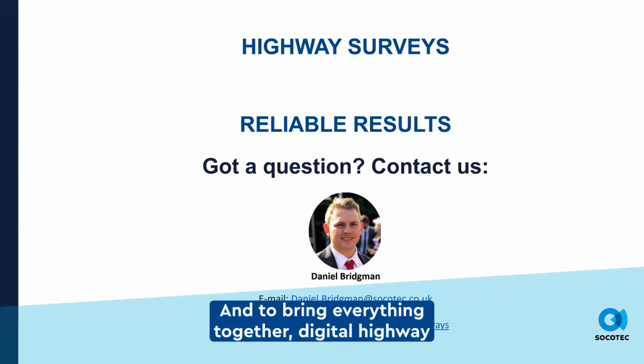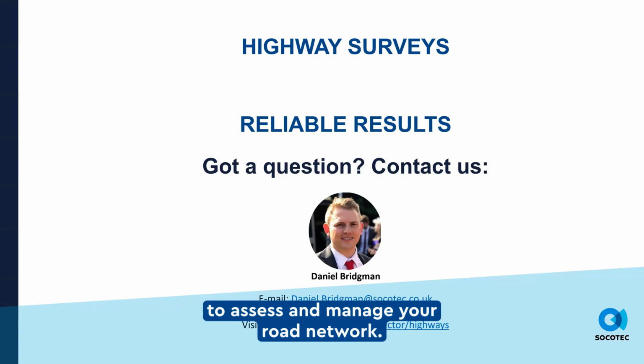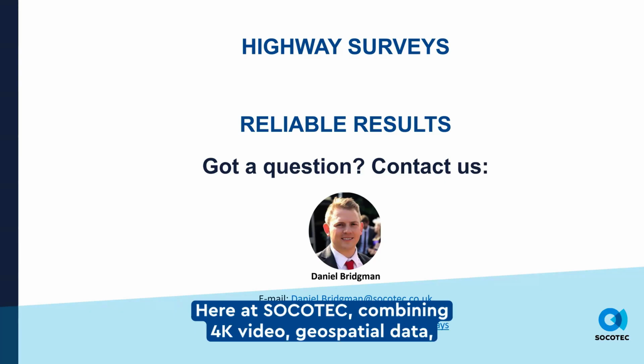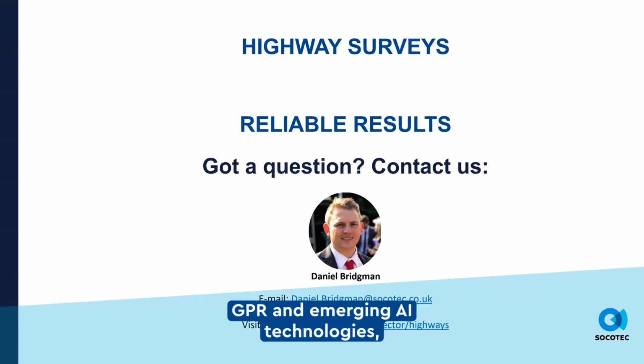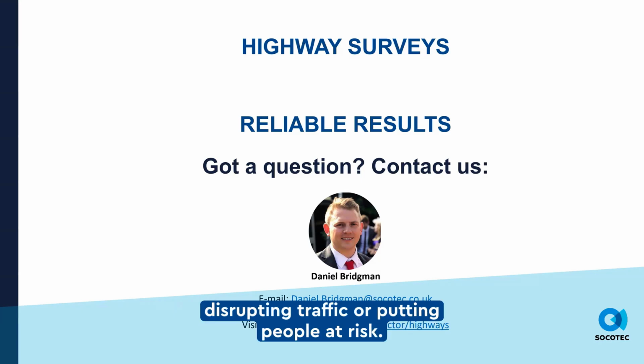And to bring everything together, digital highway surveys provide a safe, reliable and repeatable way to assess and manage your road network. Here at Socotec, by combining 4K video, geospatial data, GPR and emerging AI technologies, we aim to deliver high quality information without disrupting traffic or putting people at risk.